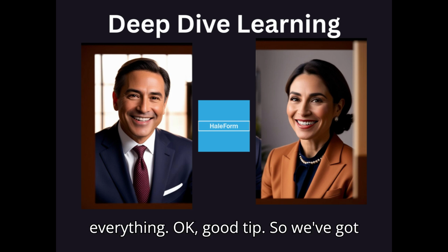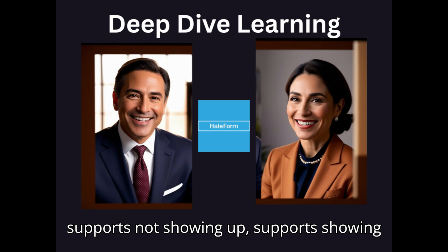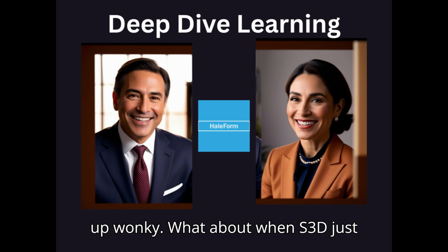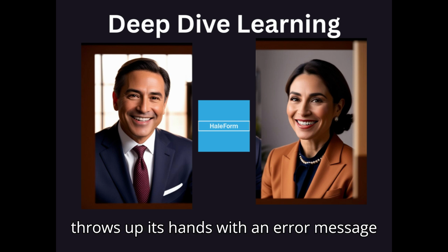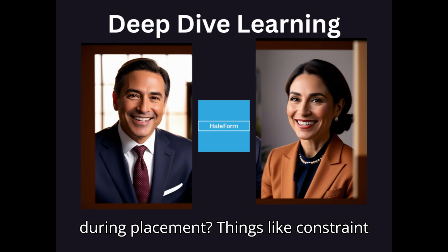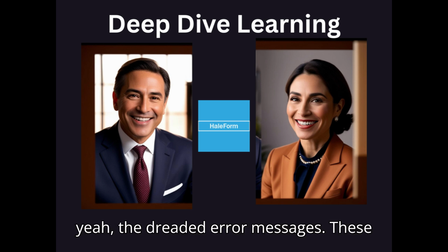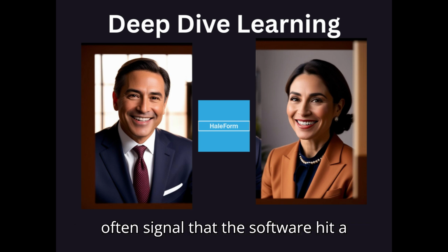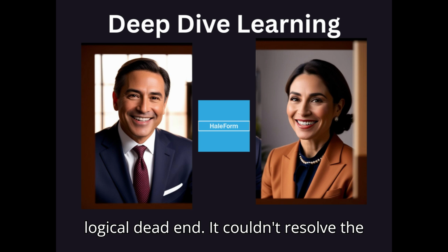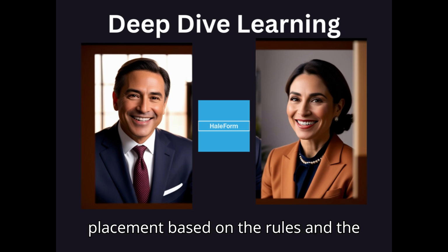Okay, good tip. So we've got supports not showing up, supports showing up wonky. What about when S3D just throws up its hands with an error message during placement? Things like constraint overdefined or failed to evaluate. Yeah, the dreaded error messages. These often signal that the software hit a logical dead end. It couldn't resolve the placement based on the rules and the geometry.